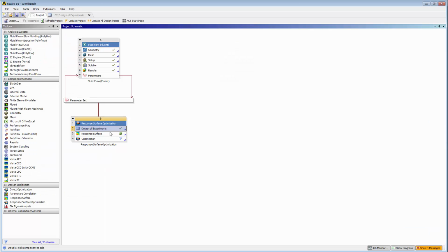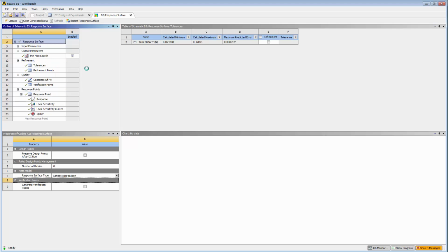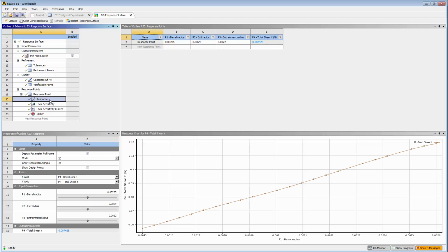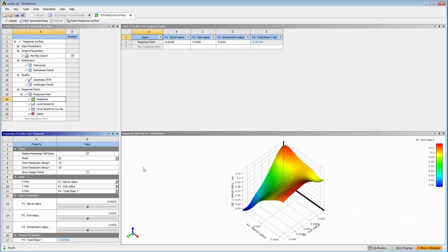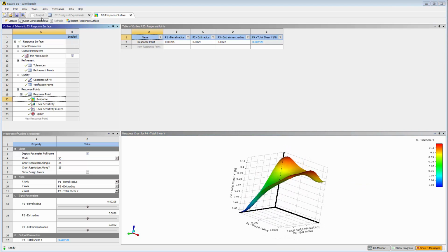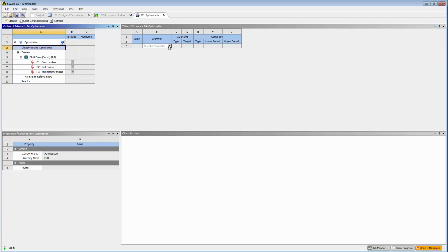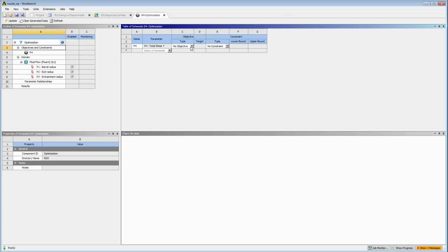From the values generated by the design points, the response surface optimization system creates a response surface. Using an interpolation method, the location of the optimization targets are determined from this surface. To find the geometry that produces the maximum total force in the Y direction at the impact surface, I'll set an objective in the Optimization tab and maximize this variable.